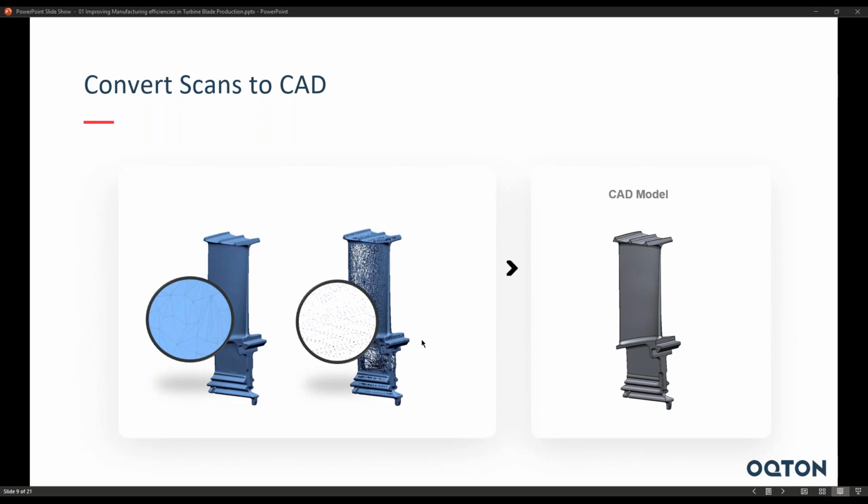but those are a bunch of triangles connecting together to form that surface. And then another form of information that you get from these 3D scanning devices is a point cloud, which is a very similar type of data set. Polygons are just a little smarter because we take those measurements and connect them together into triangles, where a point cloud is just a bunch of 3D measurements in space. And sometimes they have information as to the direction and color of each dimension. But the problem is this type of information does not fit well in the CAD environment. So that's where DesignX is going to take this type of information, these scans from point clouds and polygons, and get them over to CAD.